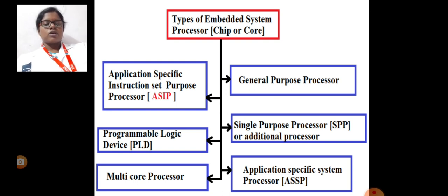Charge pump power supply system. Network interface card and graphic accelerator are examples of embedded systems that do not have their own power supply and connect to PC power supply lines. The current consumed at any instant in the processor of an embedded system depends on the state or mode of the processor. The following are the typical values in 6 states of the processor. First one is 50 mA when only the processor is running, that is, the processor is executing instructions.